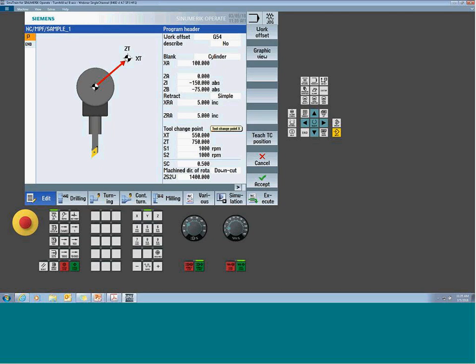So this is a value that I like to get very visual with when I'm out on a machine. I'll pre-position the tool in a safe location. With these B-axis machines, I certainly want to think about the swinging of that B-axis, maybe with the lowest tool potential. I want to try to get as far away as possible. Some of these machines get pretty compact, so you've got to be careful starting to swing things around.